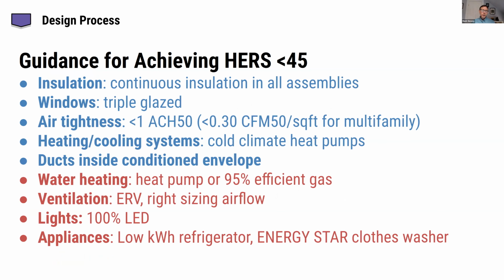So I think a lot of people have become accustomed to what's needed to hit a HERS index of 55 because the stretch code has required that level for a while now. And you can have somewhat of an intuitive design process where I'm designing a pretty efficient building. Let's see what the index is, but I'm pretty sure it'll be enough to meet the stretch code. For meeting an index that's better than 45, it will take some time for designers and everyone else to get used to what we need to do to hit that type of index.